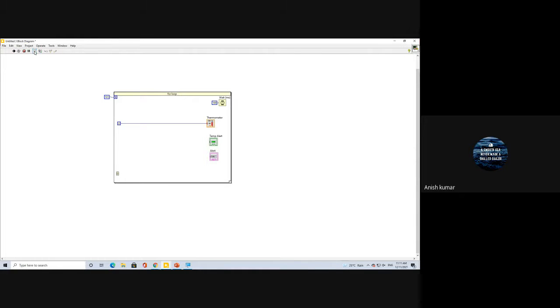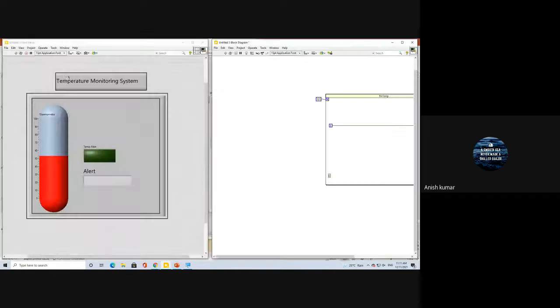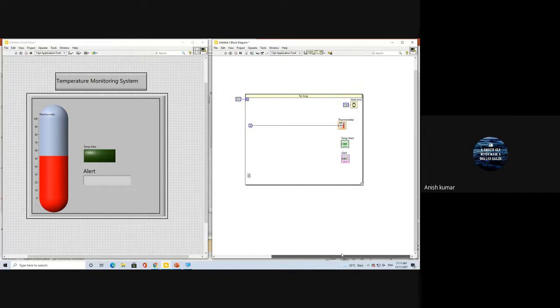Like if I give this highlight execution, you can see the data flow here. So this is for debug. This will be helpful for debugging your program, right? So you can see the data flow. So now 38 iteration is going on, and here 100 milliseconds. So you can visually see what is the data flow, right? And you can run here or there, both sides you can run it. Both are same.